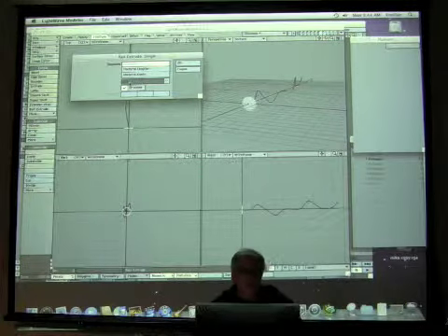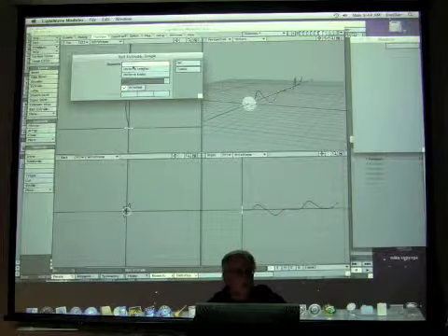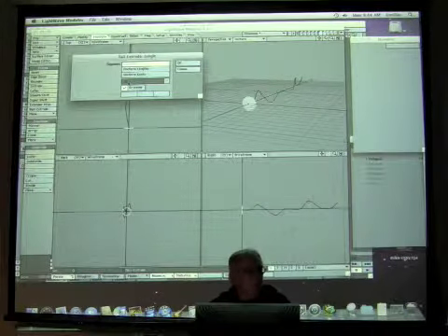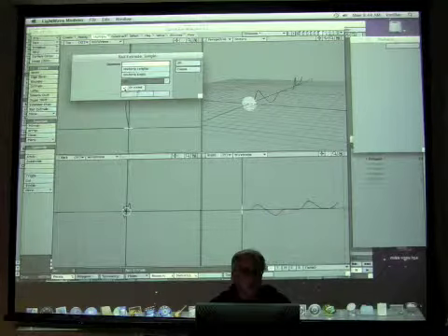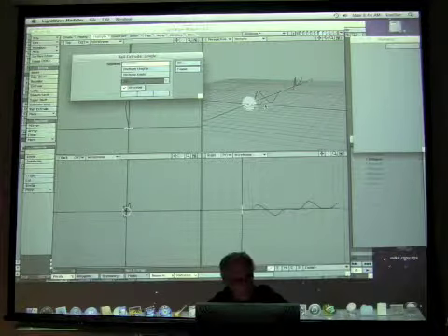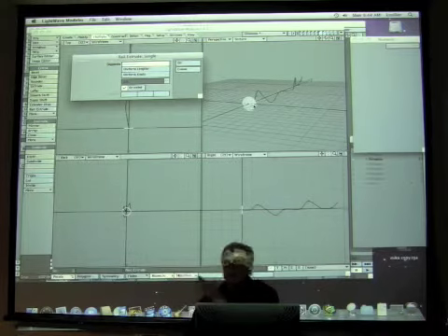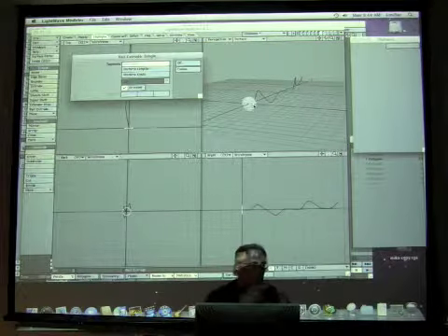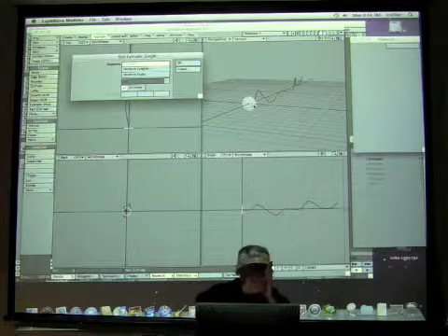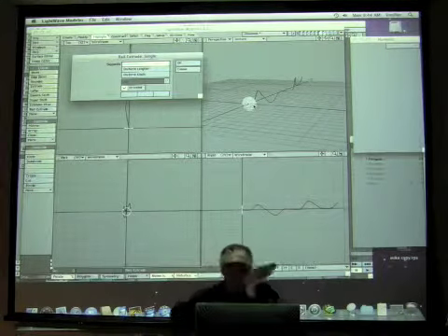And it will put 20 knots in here, meaning it will use 20 divisions in there. You can also do uniform lengths and uniform knots, and you can specify the number of knots that you want in there. You can also make sure that it is oriented to path. And that is important if you want to make sure that it follows the path in a uniform way, then you have to make sure that whatever two-dimensional shape you start with is perpendicular to that path from the very start. Does that make sense? If it's tilted, it's going to extrude at that tilted angle.